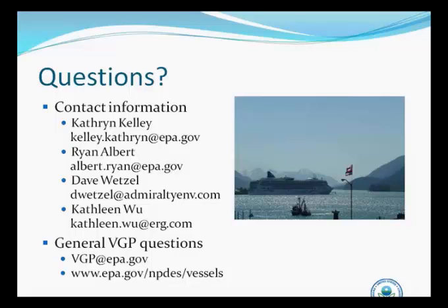And just while we're on that subject, there's another question here that's very similar, but asks the question for exhaust gas scrubber effluent. Do only new vessels need to monitor exhaust gas scrubber effluent? In that case, it's all vessels that have exhaust gas scrubber systems. So we don't distinguish whether or not you're a new build vessel or an existing vessel. If you have an exhaust gas scrubber system that has a wash water effluent, then you need to monitor. That one's a little more general. Great, thank you. We'll take Kate off the Inquisition block now and switch over to Kathleen.